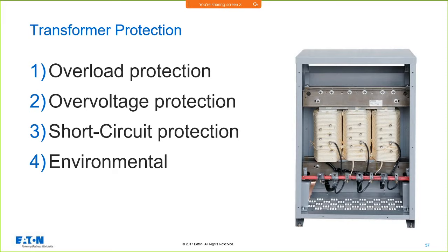From an environmental perspective, I don't have too many slides. I don't think I have any slides in here. I pulled out a bunch of the stuff around. There's code requirements that tell you you're not allowed to put stuff on top of these transformers, and we just did some changes. They're worried about the ventilation. You're not going to install a transformer that's designed for the inside in the outdoors. So you have to follow equipment ratings, etc. That's all very important parts of this equation. I'm going to focus primarily on your overload and short circuit protection in here.